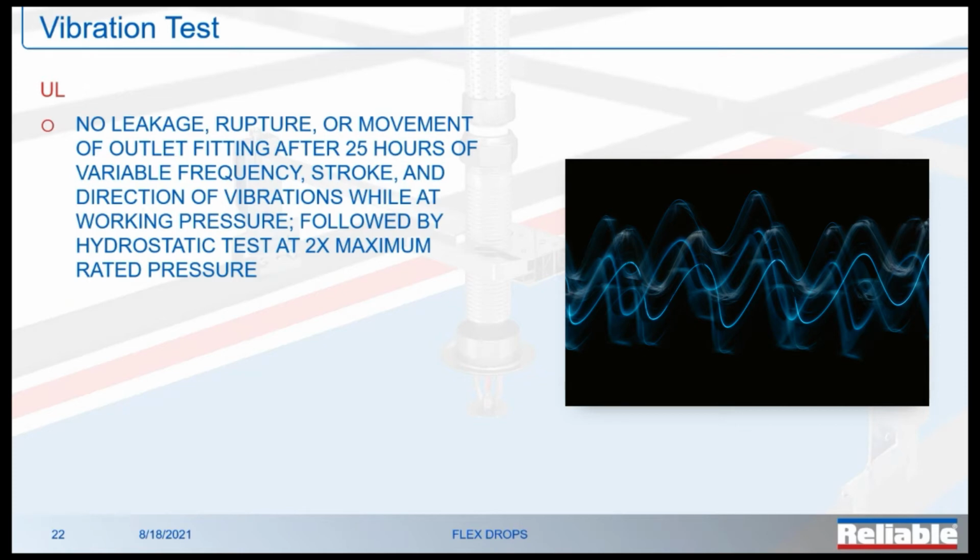At UL, they're going to vibrate it left and right, from you and away from you, and up and down. And they're going to do this at a number of different frequencies. These are all spelled out in the test standard. And afterward, they're going to hydrostatically test it at 2 times the maximum rated pressure.